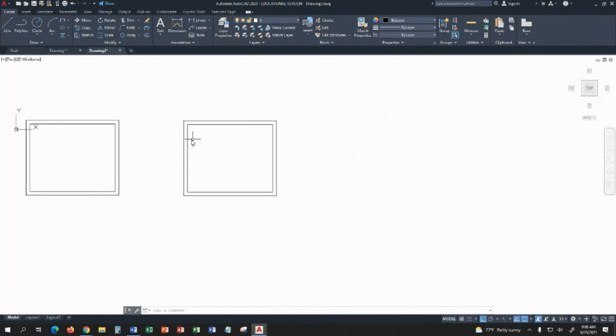So now when I look at this, this is 4 lines, is 8 lines. Next, I want to fillet this corner. So I'm going to fillet it, and I'm going to pick my radius. It was 0 before because I was doing 45 or 90 degree angles. I'm going to pick 12, and it says select, it'll tell you what to do. So it's asking you to select first object. So I select the first one, I select the second one, I've got a radius.